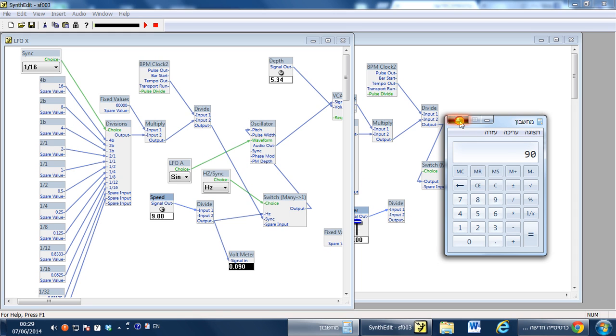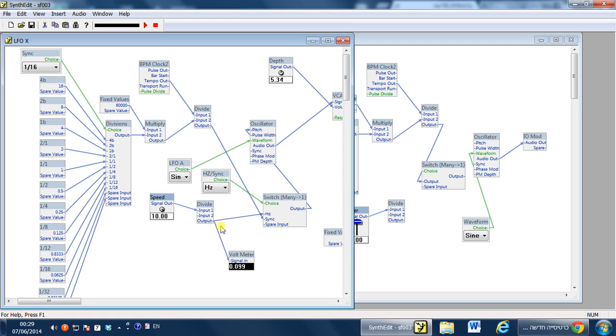And that's on 9. So our LFO, after we go through the divider, is scaled to 0.01 hertz up to 100 hertz basically. So it's a low frequency oscillator that is going just a little bit into audio rate. Now we could have obviously band limited it down even more, but 100 hertz is cool. I decided to have the ability for the LFO to go a little bit into audio rate. You can have it go more into audio rate if you want to, but I'm just showing you the technique to scale the speed of the LFO.